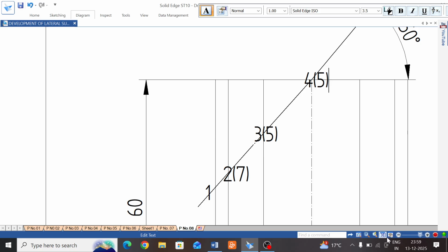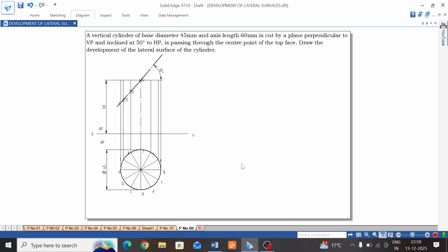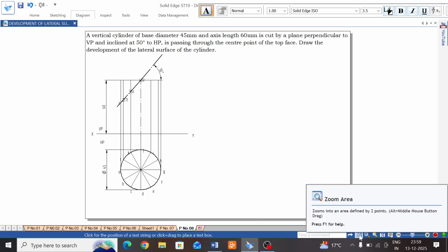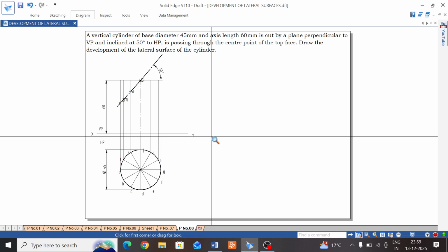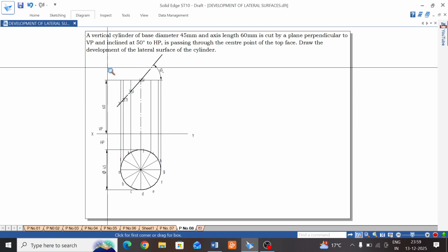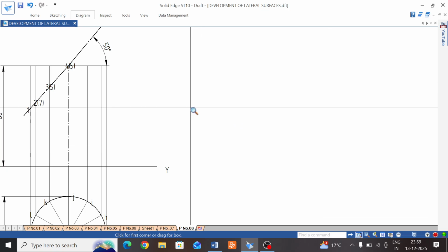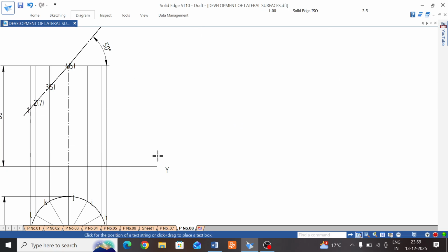The bottom, top view, front faces are visible, A, B visible, 2, and this last point is invisible, C visible, back one is invisible. Those naming is done. Now make use of the zoom command and project the parallel line method. Parallel line method, we have to draw this.